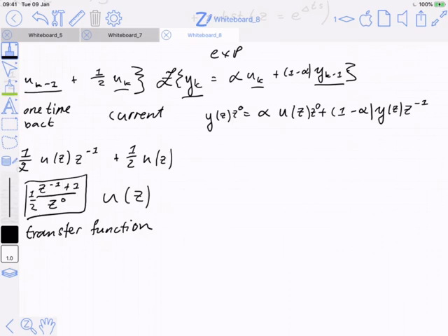So here we again have, but now there's a little bit of extra solution step, right? Because now we've actually got 2 occurrences of y. And so we now have to do roughly the same thing. You'll see you're using the same skills that you picked up doing transfer functions in the Laplace domain. Because once we've done this transform, it's again just polynomials in z. And so here we have y of z, and we've got to take it out.